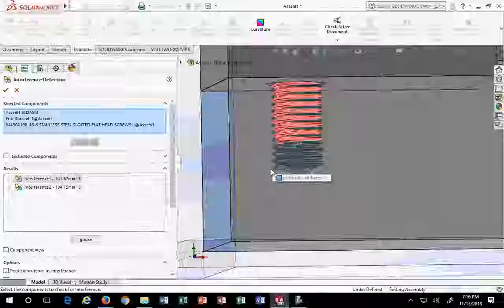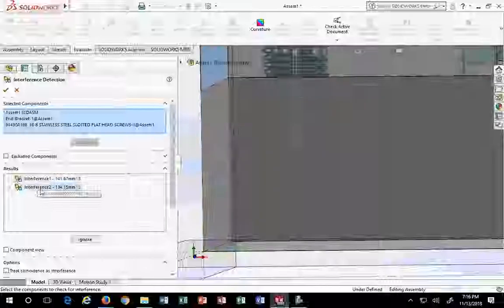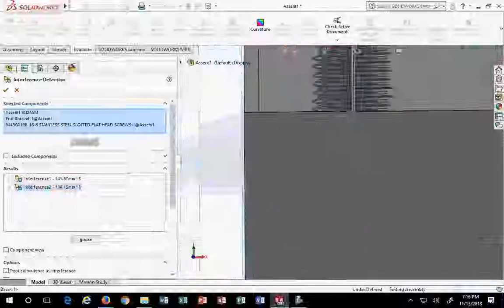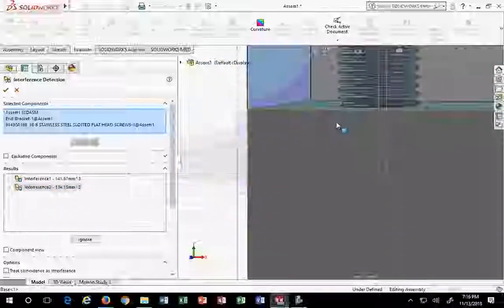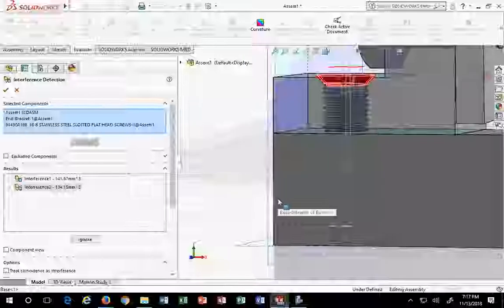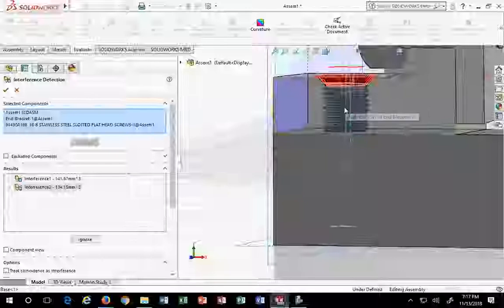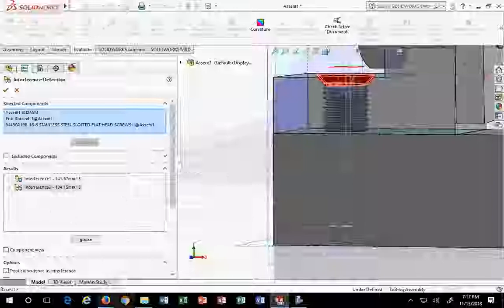At the bottom. You don't see it on the top one. Why? Because technically the hole is bigger than the thread. It's a clearance hole. It's the only reason there's no interference up there, in this neck of the part, because the hole itself is physically bigger than the thread. That's how it was drawn or requested.